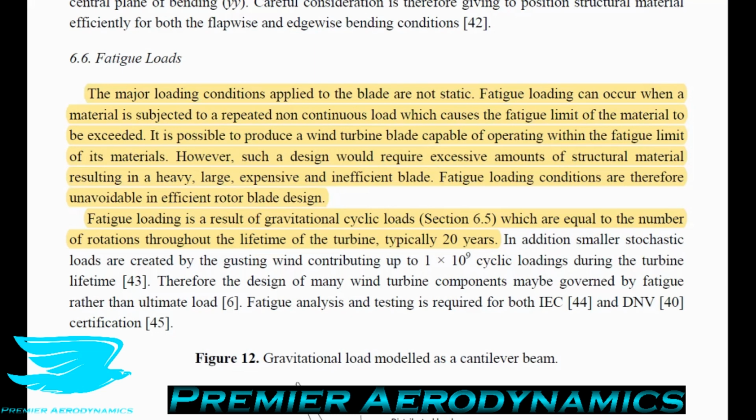It is possible to produce a wind turbine blade capable of operating within the fatigue limit of its materials. However, such a design would require excessive amounts of structural material, resulting in a heavy, large, expensive, and inefficient blade. So fatigue loading conditions are therefore unavoidable in efficient rotor blade design. So let's cover that in English. What they mean is, if you want to design a wind turbine so it can withstand fatigue loading, then it has to be very heavy, and that's not feasible.